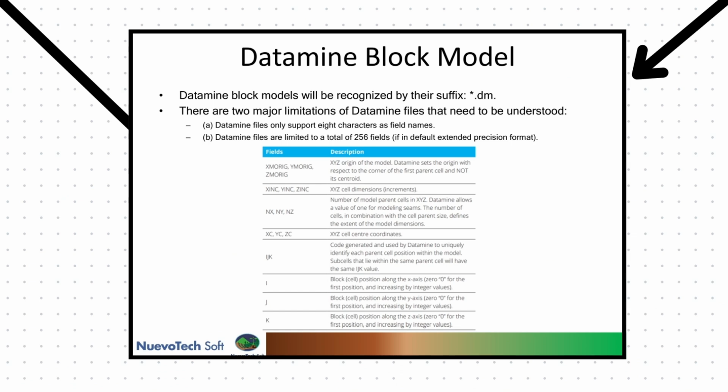Datamine block models come in two precision modes, the single SP and the extended EP. The original SP files were stored in 2048-bit pages. Page 1 defines the overall schema and the subsequent pages hold the records. In simple terms, the first block of the data explains what each field is, then the rest of the file lists the blocks. Datamine also has text alpha and numeric data types.